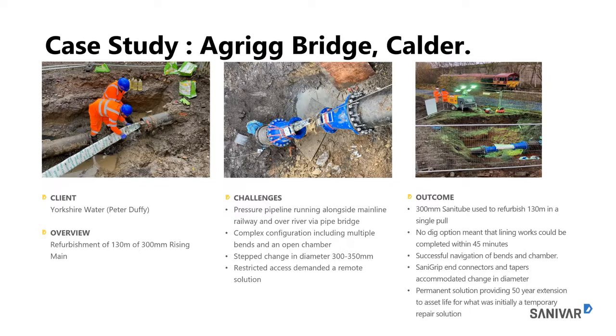You can just see the liner emerging in the middle picture on the left-hand side of the two tapers, and then inflated, tested, pieced up with Sani-grip, and then bolted onto the flange ends of the taper to get a seal, which I think you can't see, that hasn't been sealed off on the right-hand picture.